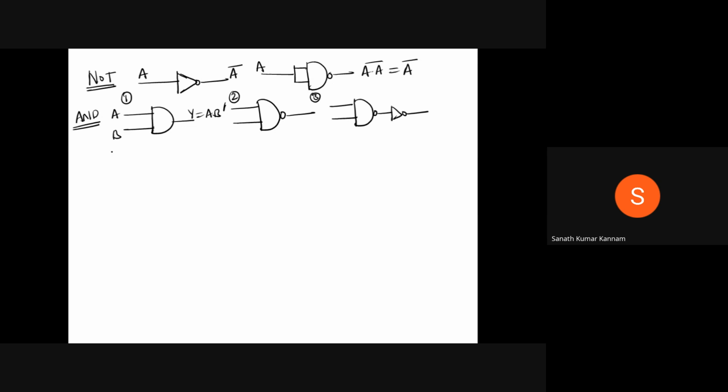After that, replace all the gates with the equivalent NAND gates. So this inverter I am replacing with a NAND gate. Here with A, B, you are getting (AB) whole bar. The complement of the complement, we are getting AB. So this is the AND gate. Did you get the concept of how I realized the AND gate?